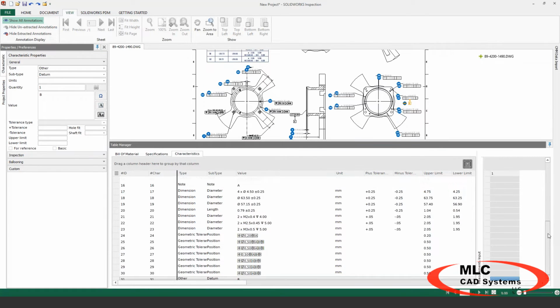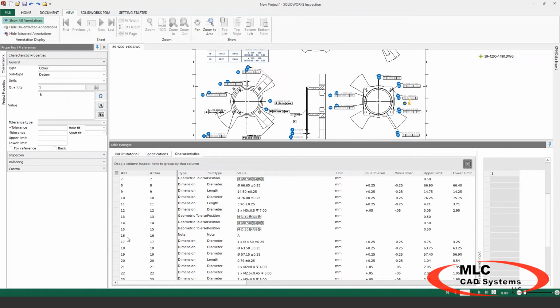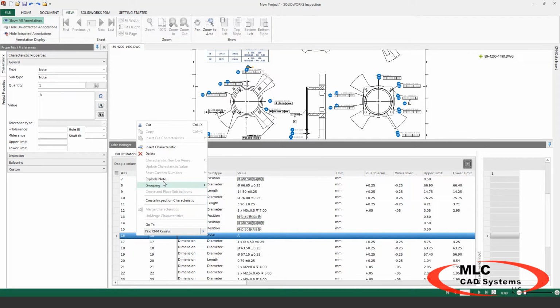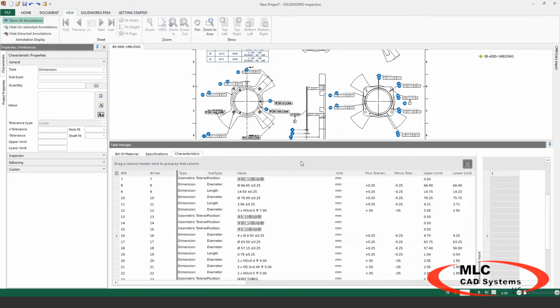this looks like here. Now we're grabbing a lot of information all at once, and there may be items such as number 16 where that's actually my datum A. I don't necessarily need that. I can easily reorder, delete items. When I delete these, the numbering is going to automatically update so I'm not missing a digit. And it's very easy to reorganize and capture all of this information.